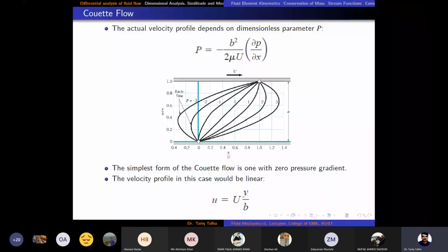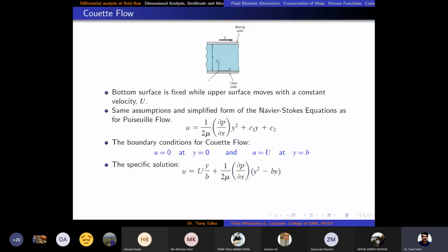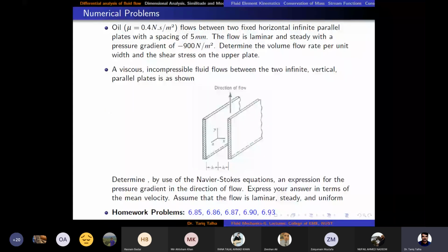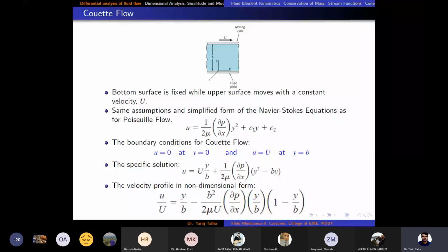Now this was just about the derivation of the Navier-Stokes equation for the compressible viscous flow, right? So now, as you can see, we can only get the exact solution for very simplified cases. We cannot get the solution when we have got unsteady flow, or multi-dimensional flow where u is also a function of x and y and z, which is the case when the flow goes through certain turbomachinery applications, or flow over an aeroplane, or flow over a vehicle.